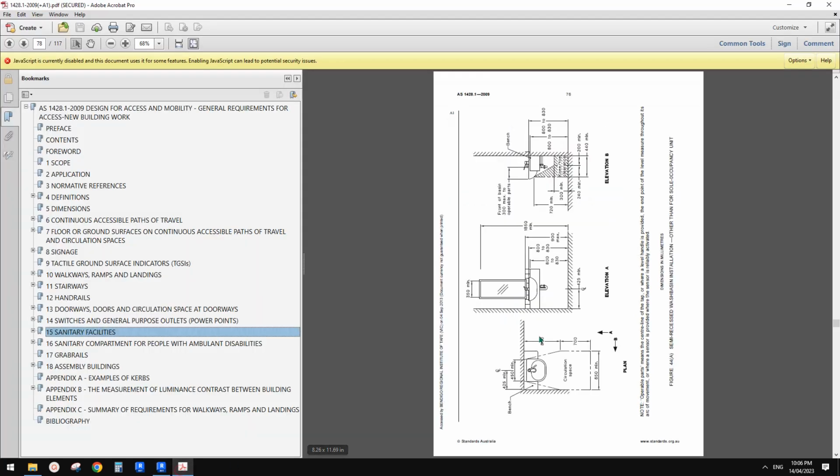For the mirror, anything we need a height. For example the mirror needs a maximum of 900, and it's also being placed onto a vertical element, so we should consider modeling it using the face-based family template.